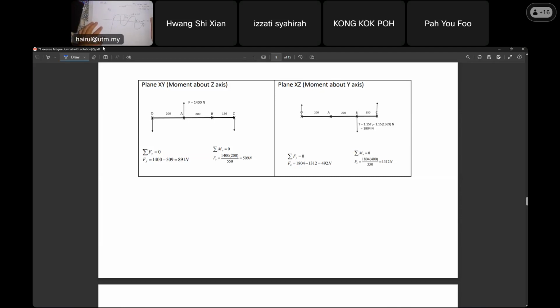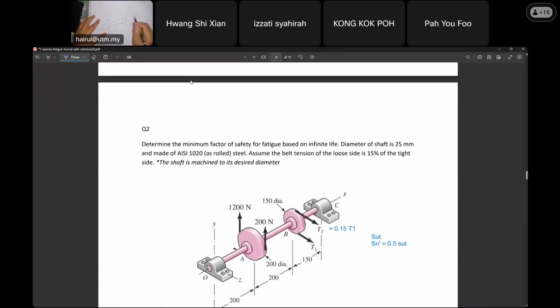But now I am asking you about torsional stress. At B we have torsional stress. What about torsional stress at B? Logically, class, look here. This is the big pulley A, and this is the shaft. At the back we have the small pulley, but B is critical for bending. So the loading is like this. We have torsional stress. We have torque 1 and torque 2, and we know the values, we already calculated. At B we have torsional stress.